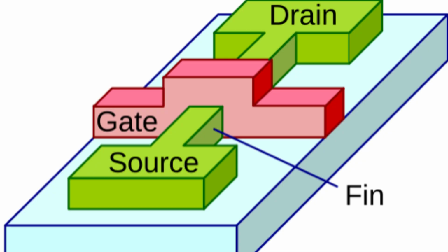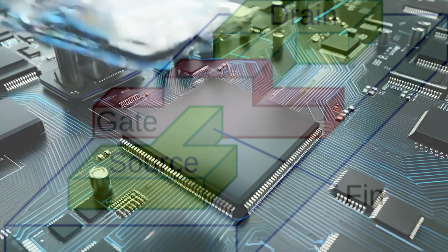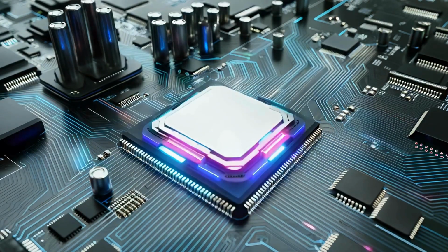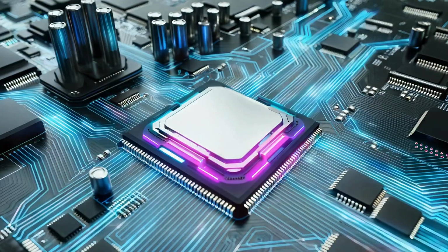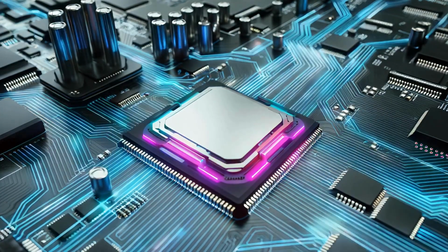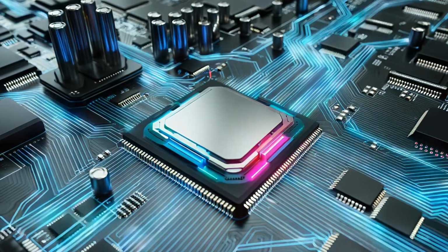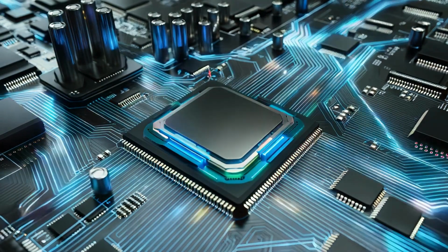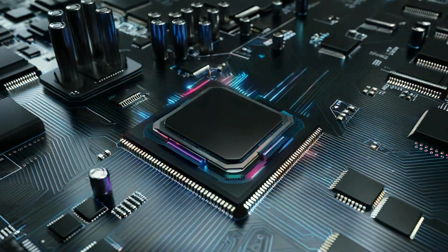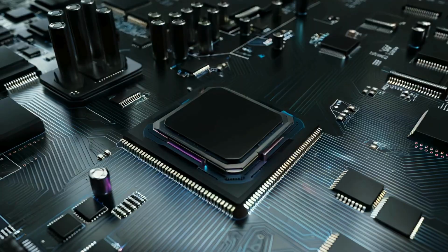FinFETs, fin field effect transistors, emerged as we scaled below 22 nanometers. Instead of a flat channel, FinFETs use a thin, fin-shaped silicon body that the gate wraps around on three sides, offering better control over the channel and reducing leakage currents.